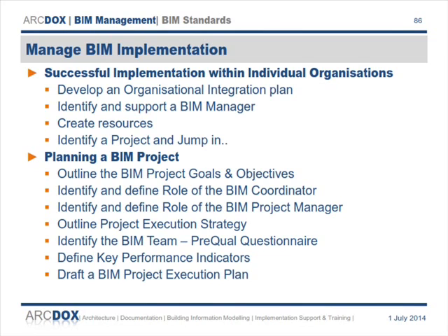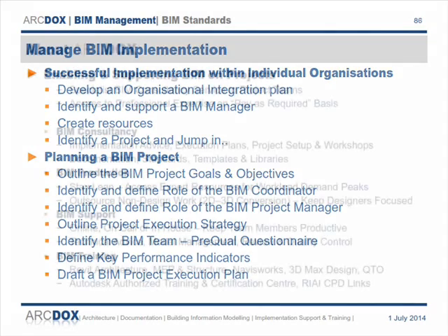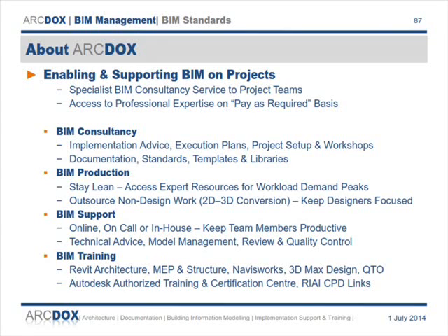Jump in. So plan it, outline the project goals, identify the roles of the various people on the project, outline an execution strategy, pre-qual the team, define KPIs, and draft a BIM execution plan. Right at the beginning, once you've got your client's requirements down, draft a BIM execution plan, even if it's not the final document. Draft it so everybody knows what to do.